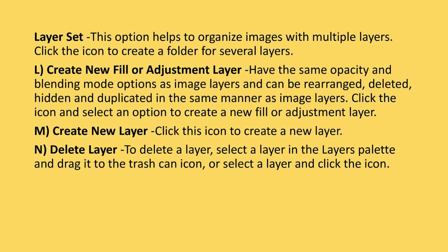Next is layer set. This option helps to organize images with multiple layers. Click the icon to create a folder; layer sets have blending mode options like image layers and can be rearranged, deleted, hidden and duplicated in the same manner as image layers. Click the icon and select an option to create a new fill or adjustment layer.